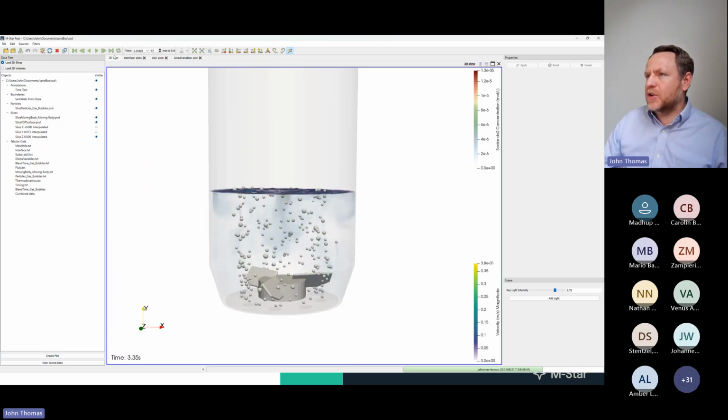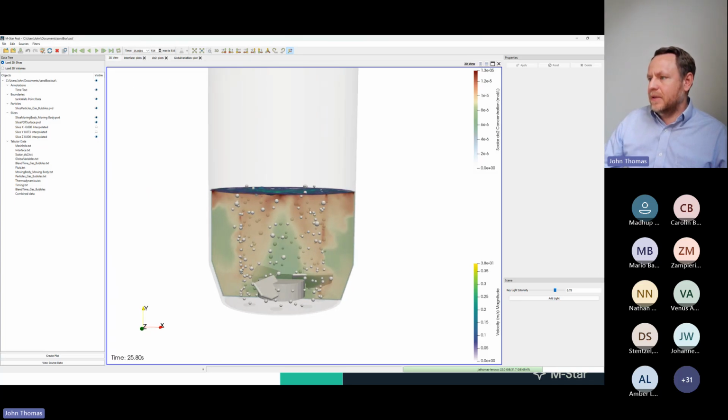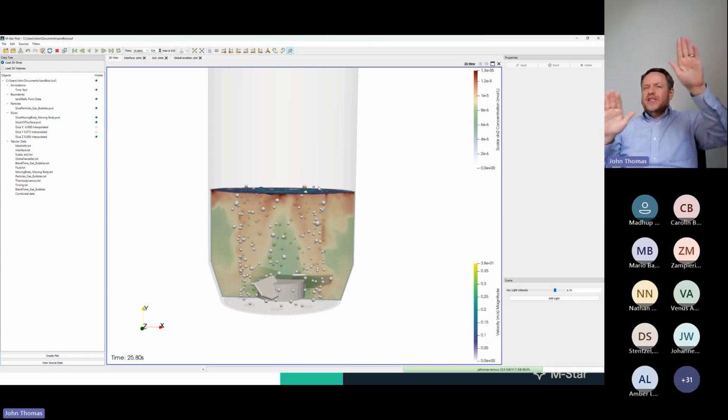So if we had no sparged gas, the only oxygen source would be the free surface, of course. We can then see how it's mixing and going throughout the system. We could also, if we wanted to inside the model, color these. We could have oxygen 1 and oxygen 2, and see where oxygen from the headspace got to, where oxygen from the bubbles got to, and see if there was some sort of disharmony between how they were mixed. I don't think that would happen, but you could do that. Then you sum them together when doing reaction kinetics. But to be sure, you could do these as two different species, with purple and yellow oxygen, and see what ratio of oxygen came from what spot. That'd be kind of academic. It would be interesting.